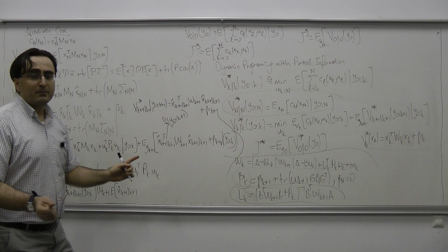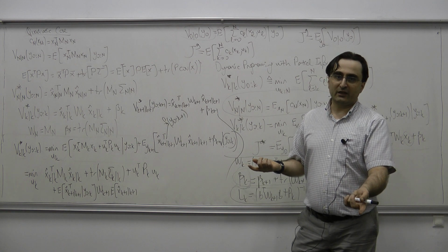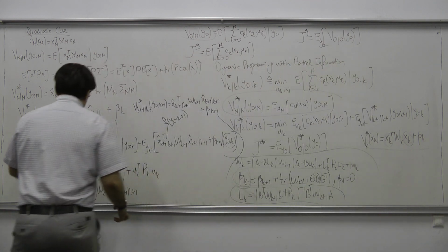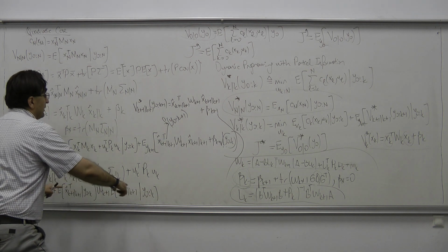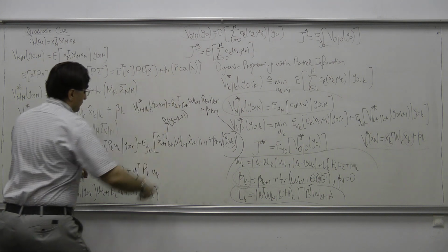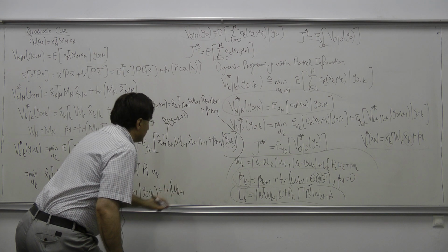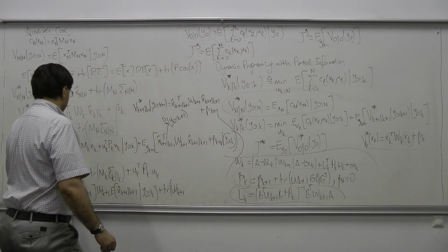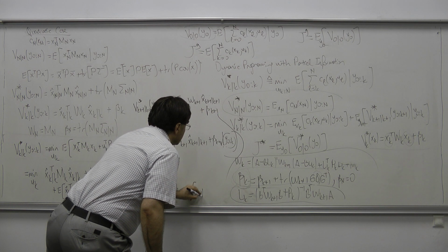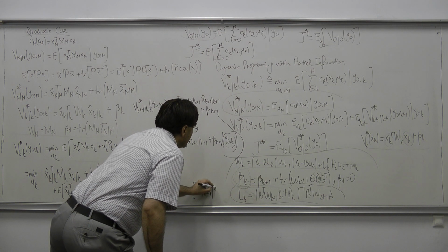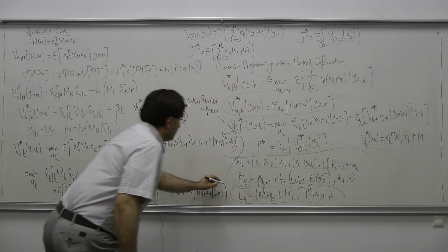Now you need to think about the Kalman filter estimate as a random function of the measurement yk plus 1, okay, and given y0 to k. This is the expected term, it is this one, and then I would have the trace term plus trace of this matrix Wk plus 1 times the covariance of this estimate, the covariance of x at k plus 1 given k plus 1 hat given y0 to k, okay. I close the trace.